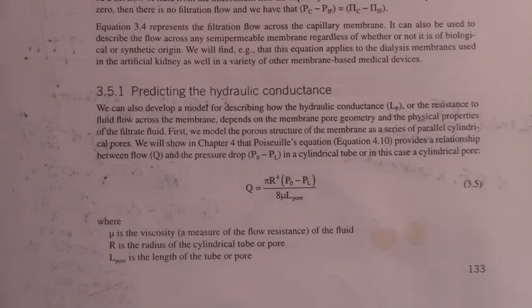Turbulent flow is very chaotic. And if you go in your kitchen tonight and you turn on your faucet, very low flow, you see that nice, clear, glassy stream coming out of your faucet, that would be laminar flow. If you jack the flow rate up real high, it becomes turbulent. It gets cloudy, it's crazy looking. That's turbulent flow. Well, in any case, the nature of the filtration flow through the pores of a membrane would be laminar flow.